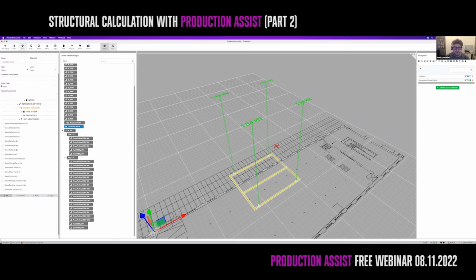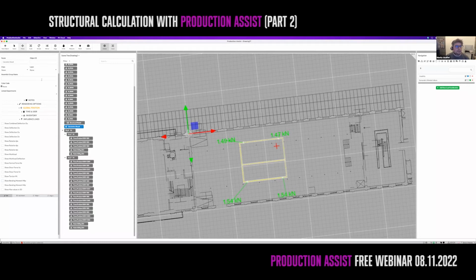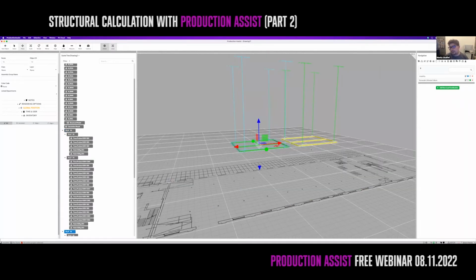The next thing we are going to do is that we want to have 2 of these pieces because we want to align them to the actual house points in here. So what I'm doing is I move this a little bit to the right so that it's like this. And again, I'm selecting the red arrow, hold the Option key and move it so that I can duplicate it and have 2 of these truss systems in here. Releasing this will bring you the new trusses, so you have 2 of them and you can insert them.